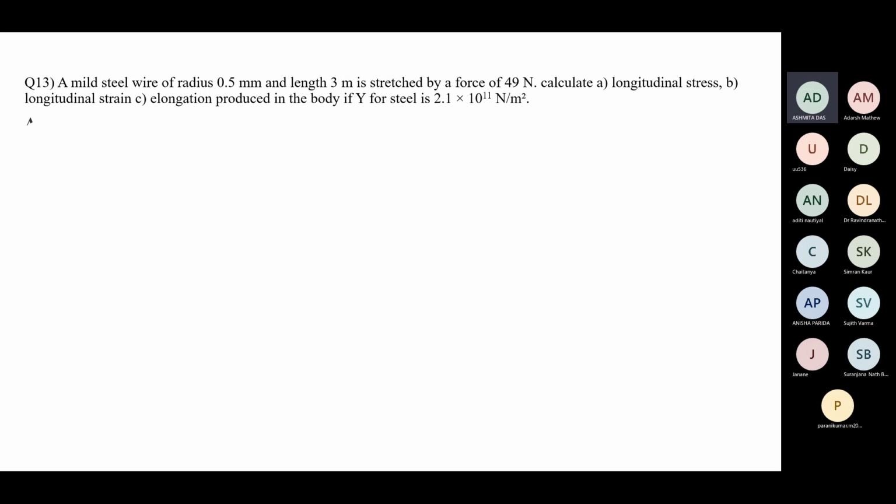Now Y is equal to stress by strain. So strain can be calculated as stress divided by Y. Stress is 6.238 into 10 to the power 7 divided by the Young modulus, which is 2.1 into 10 to the power 11. After calculating, the strain value comes around 2.97 into 10 to the power minus 4.